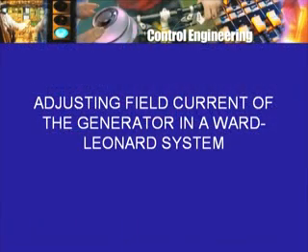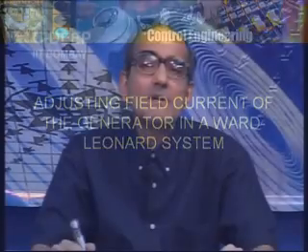So in a way it is making an adjustment of the field current, but not adjustment of field current of the motor, but adjusting the field current of the generator. So you can imagine a Ward-Leonard system in which the operator still plays a role. The operator adjusts the field current of the generator rather than adjusting the field current of the motor. Now if the operator is to be removed, we have to put a mechanism or a controller which will change the field current of the generator field winding. Now how is this adjustment to be done? What mechanism? And there are of course several alternatives.